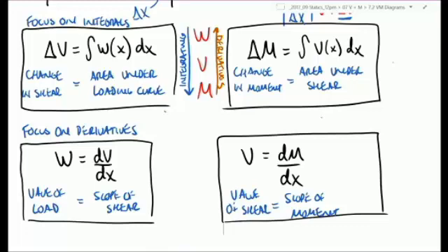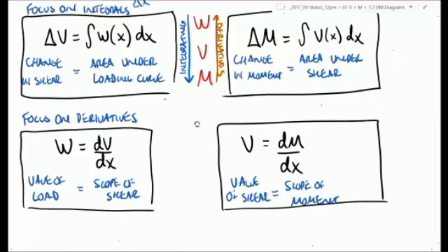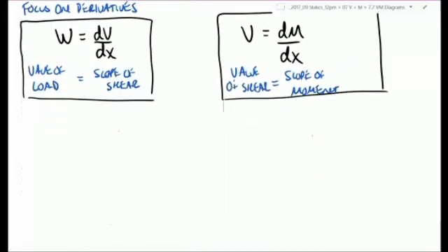So we'll be given one of these equations, and then we just calculate the other two. Yeah, fundamentally what we end up doing, and actually let me just go through this example. So the question was, would we be given one of these and would we be doing the calculus? You often start at the loading. What is the loading? And then you work down from loading to shear to moment. So let's look at the standard flow of a problem. This isn't going to be a full numerical example. This is really just going to be more of a process example.